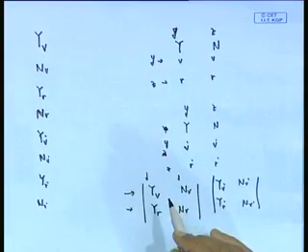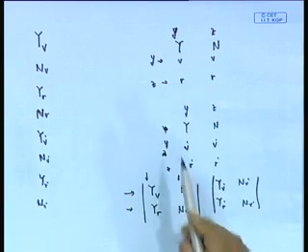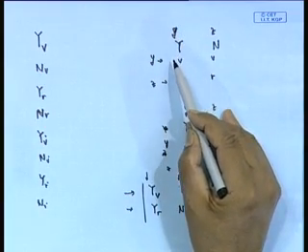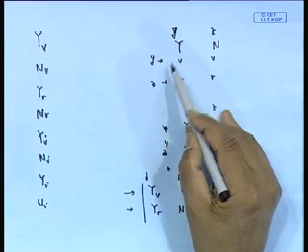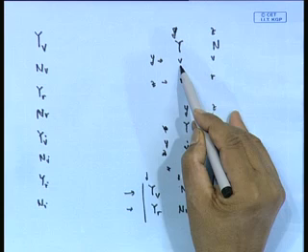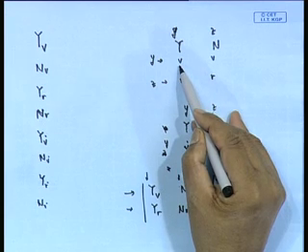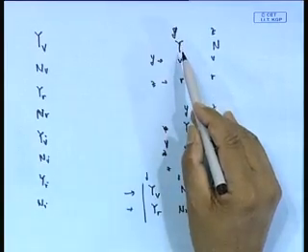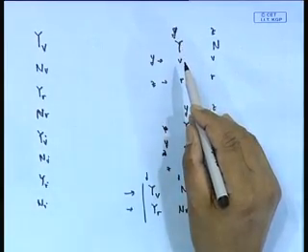Once again, let me explain that. Yv is force in the direction y with respect to, or gradient of that with respect to, motion in direction y, that is dy by dv. Once again, yv represents force in direction y, d of force in direction y divided by d of velocity in direction y, both are in y direction.